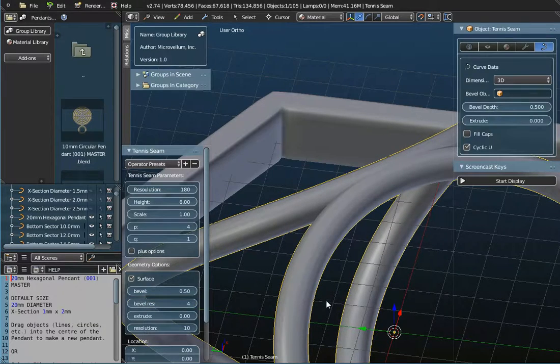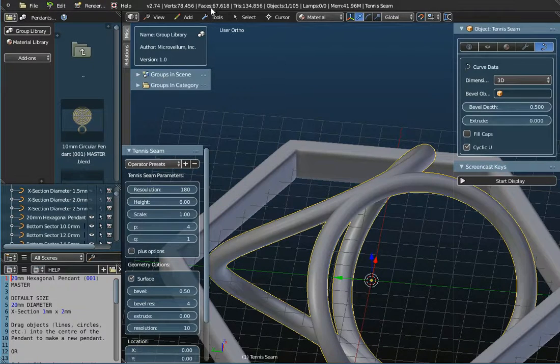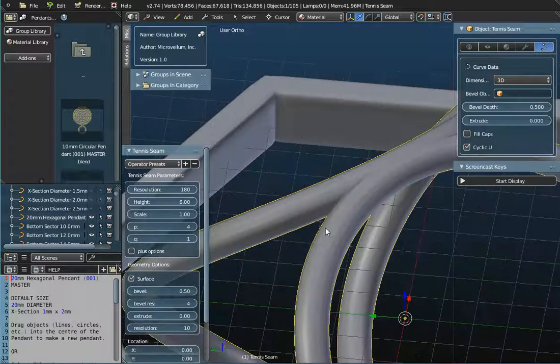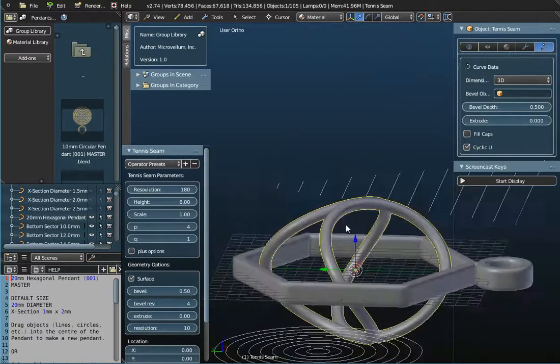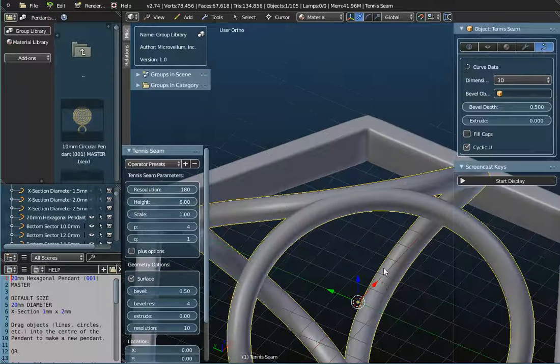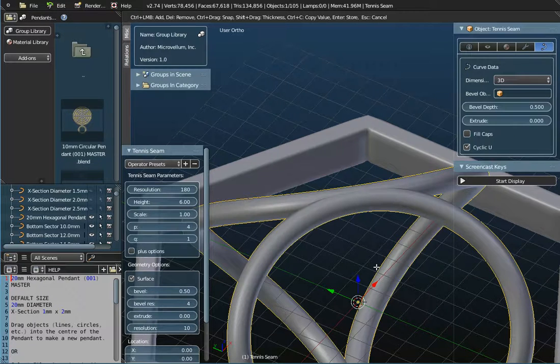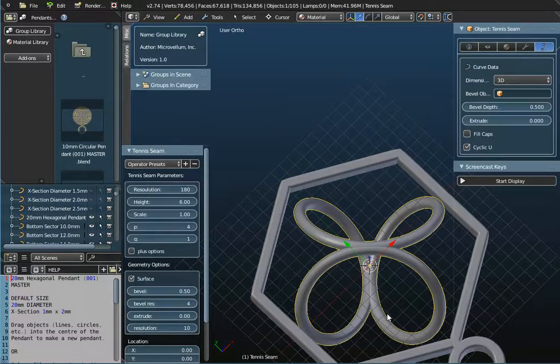So I've set it up at 4 for you, so that you get a nice, smooth surface. Now there is a downside to that, you get a lot of faces, but generally speaking with jewellery items you want smooth finishes, so that's why this is set at 4. I said with the previous object that the bevel of 0.5 represents the radius here, so the thickness again of this one is still 1 millimeter, and it's been set at that so that you can